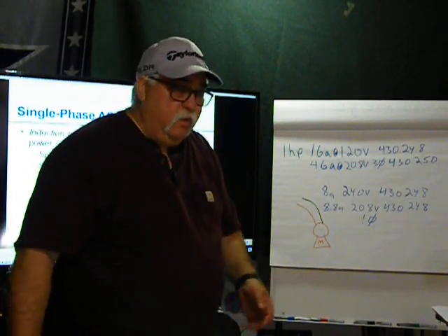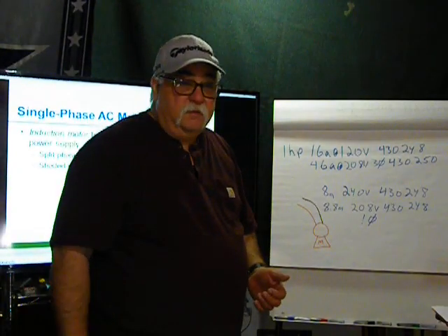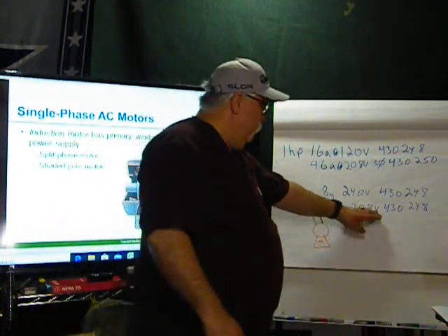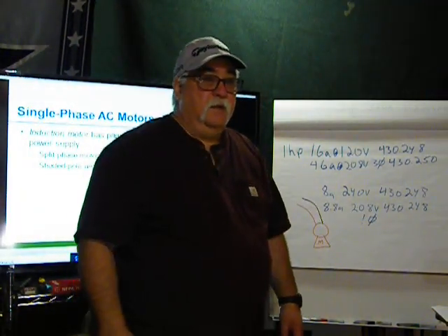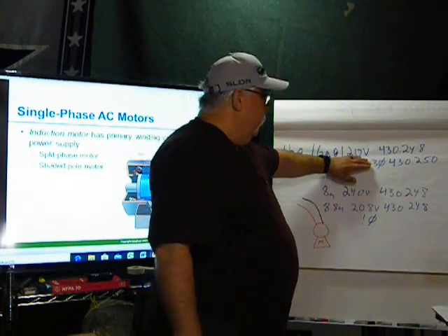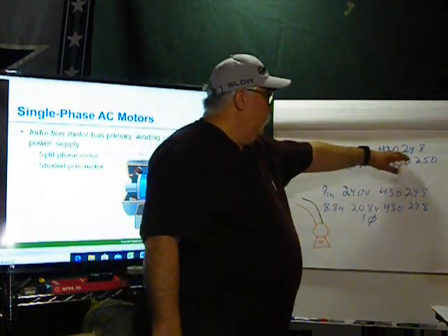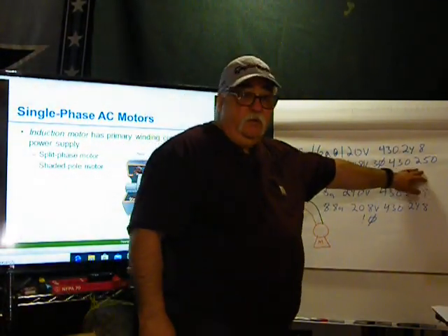Okay, when you're doing a question, hopefully they will explain that it's either single phase or 3-phase. Okay, if you got a 208 volt and they don't mention single phase, then it's automatically 3-phase. You know, if it's 120 volts, that's single phase. You know, that's 1 hot. So you would go to 430.248. If it was a 3-phase motor, then you would go to 430.250.